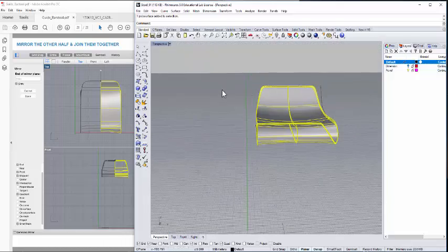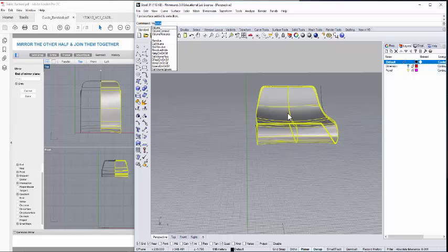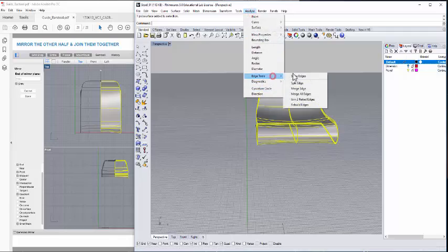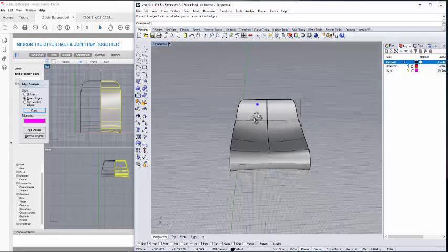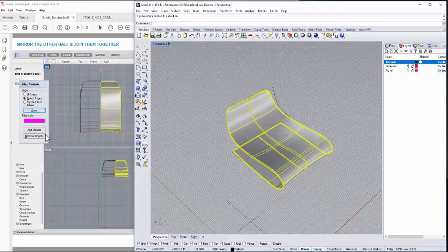So right now one poly surface added to the section. Okay, let me just double check whether I can see a volume. Yes, we can see a volume. Click again, analyze. Let me see whether the edges. Okay, it says found 14 edges total, no naked edges. So yeah, it's good.